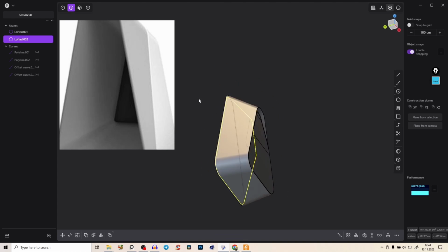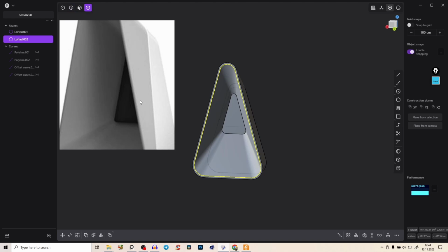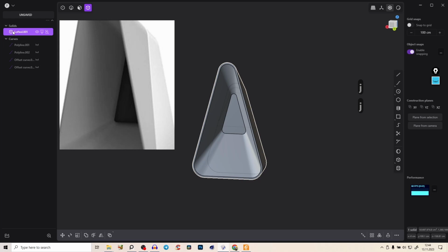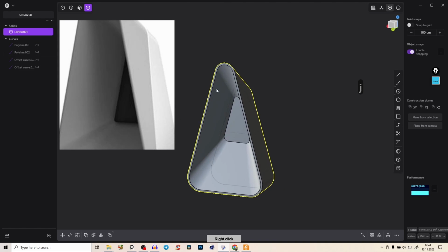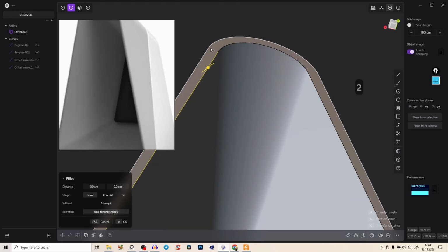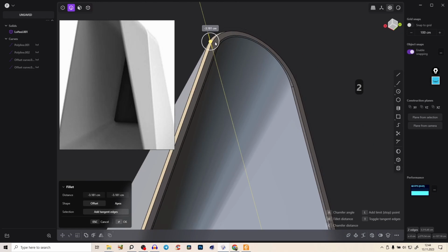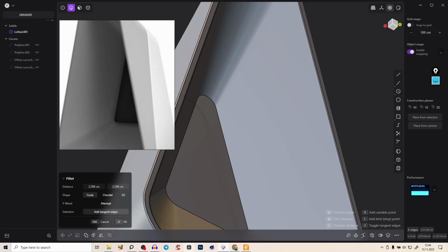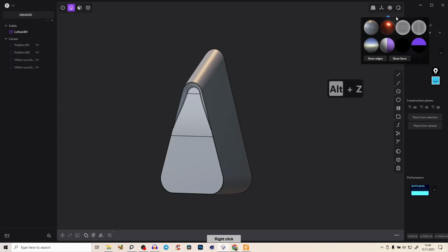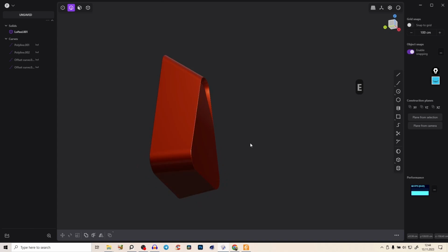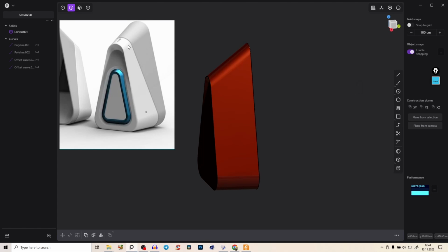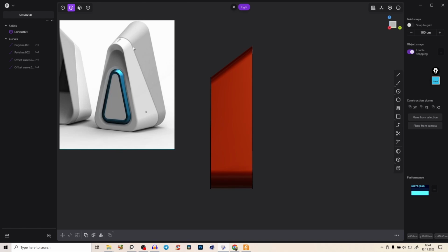So we have this whole body here. And now press object mode and select those two faces, press J to join them. And now you see we have this cube, so it's a solid. And what we can do now is select those edges here and give them some nice little fillets. You can play around, give it a hole, extrude it and all that kind of stuff. But if we check our little practice here, oh, also we forgot to break it into two pieces and give it also a little chamfer.